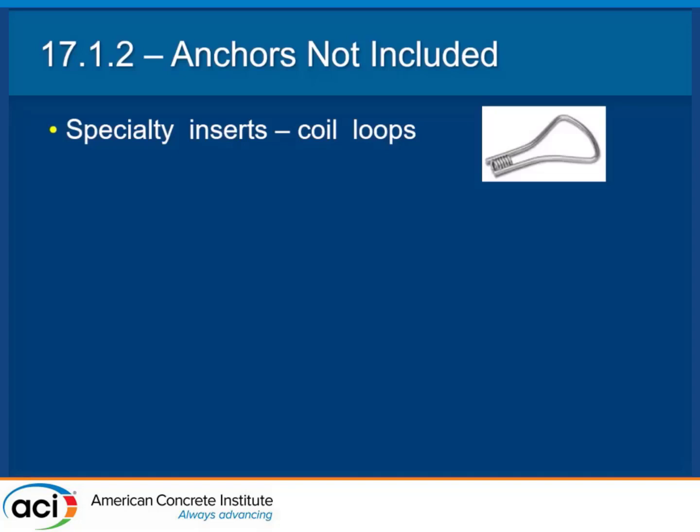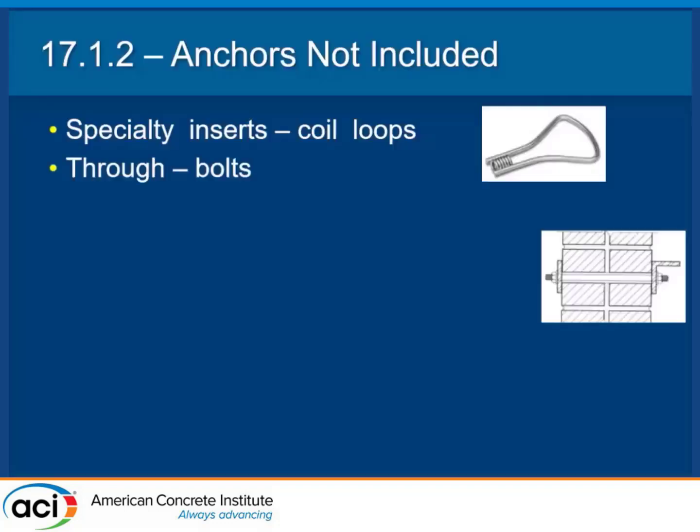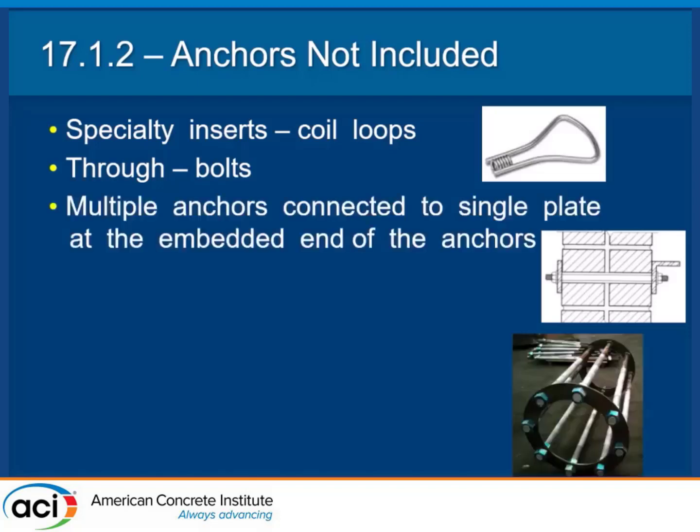Precasters love these specialty inserts and coils, but we do not cover that in the code. Through bolts, we don't cover. Now, often I get questions on through bolts. You can use a lot of the principles, and you're going to get the visuals today, to help design a through bolt, but the code does not really help you on that, or does not have any code requirements.